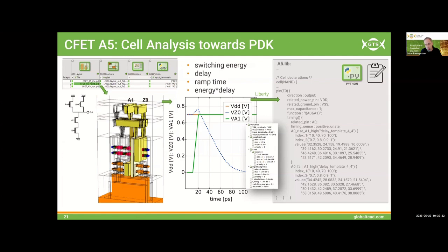Another thing, and I think that's very important to tie into the larger EDA world, is it also allows you to generate virtual PDKs beforehand, or pre-silicon PDKs. So you have your basic standard cells that you are aware of that will be out there. You know roughly what the technology roadmap is going to look like. And you want to cut down on the design times, or gain knowledge beforehand, before the technology actually becomes available to you as a designer.